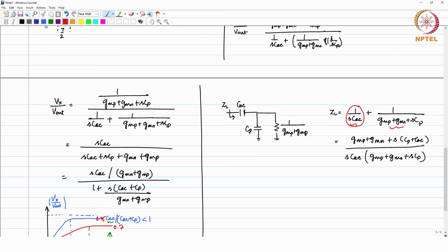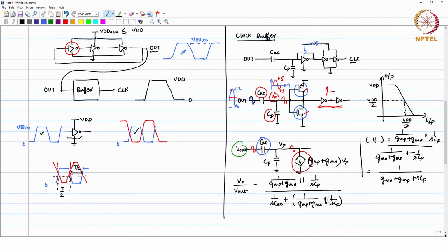If this impedance becomes negligible, this impedance dominates. In this combination, it is like the capacitors which are added up in series, right. So, if CAC is quite large and this impedance is going to be much lower, close to 0, just an example, then this impedance dominates. So, effectively you can say that this impedance loads your oscillator here at the output node.